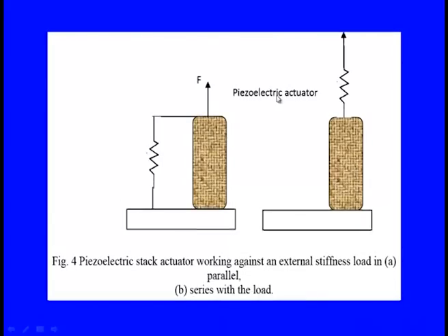So these are the piezoelectric actuators, which I am showing by the brown part, and they are working against the spring force, the external spring we can say, and they can bring the entire system to 0 amplitude by applying their forces in the proper direction shown on the diagram.